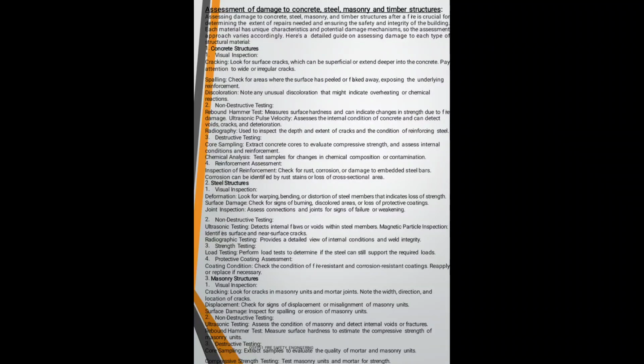Then strength testing. Perform a load test to determine if the steel can still support the required loads. Finally, the protective coating. Check the condition of fire resistant and corrosion resistant coatings. Reapply or replace if necessary.